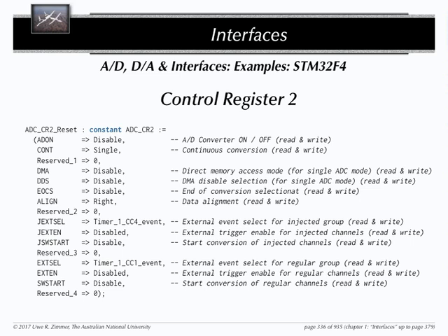And only in that level, you will need to play with that effect of taking local copies. So you don't have to do this in your actual user code later on. You have a number of abstractions in between before you get to that point. And this local copy taking is always done on the lowest abstraction level. This is only done on the level where you actually touch the hardware device registers. But I don't have any more comfortable way to express this. I don't know that there is any attribute which says always take automatically a local copy and only delay the write back until this happens or something like that. Don't have that.